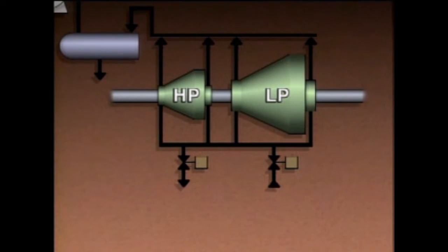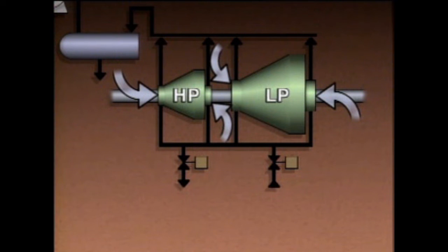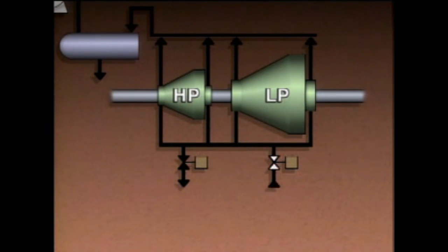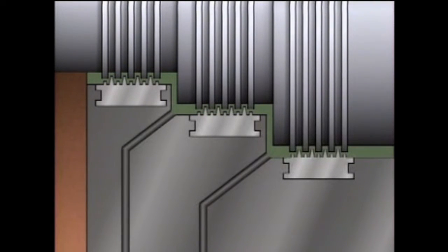The system is made up of a steam supply line, a steam supply control valve, a steam leak-off line, and a steam leak-off control valve. When the turbine is operating at low loads and many stages are under a vacuum, outside air tries to leak in. In response to these conditions, the gland steam supply control valve opens and low-pressure steam is supplied to the glands. Part of the low-pressure steam supplied to the glands enters here and flows toward the outside past the second seal. The remainder of the steam flows into the turbine.